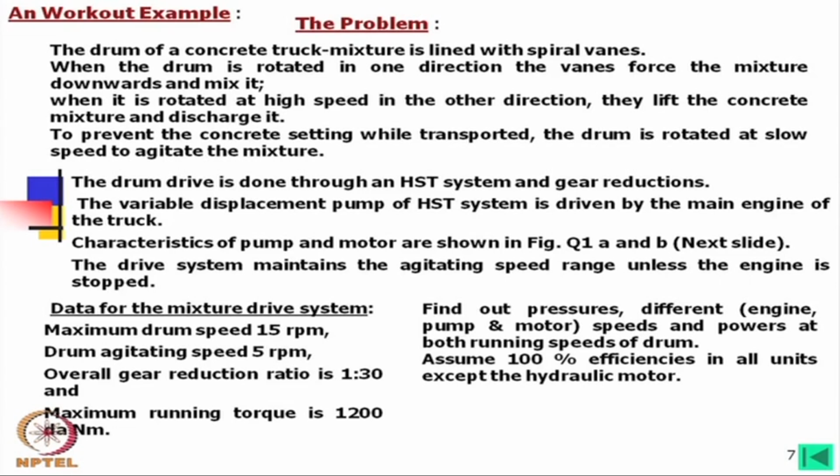Losses may be leakage losses, mechanical losses, that is friction losses, and also hydraulic losses. In this lecture we shall not discuss what all the losses are; maybe in other lectures. Leakage loss you can understand. Mechanical loss means there will be friction loss, mainly, and also thermal loss in other forms.